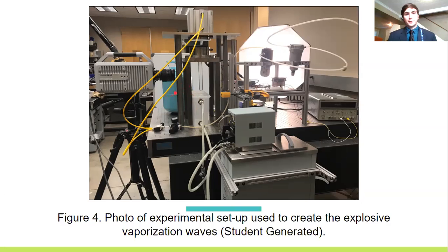And it's done with the solenoid valve connected to the R134A refrigerant tank into the testing environment. And it opens up some of the pressure inside the test tube and causes a microboiling to form on the surface level of the superheated liquid. And over time, a short amount of time actually, it will cause some of the surface level to evaporate and release some of the pockets that are underneath the superheated liquid. And once I believe enough time has passed, I'm going to seal that back off and allow condensation to continue its process of forming a liquid inside of the gaseous test tube.